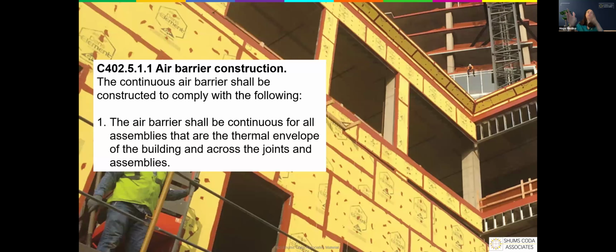All right, so air barriers. So now we're going to start hitting the sections that we're probably very familiar with. But I think after seeing what we just talked about, now these sections probably are a little bit more weighted in making sure that we get what we really need. Because remember, we do need that continuous air barrier. It needs to be continuous all the way around. A lot of times there's attention that's paid to it when we start thinking about the walls, right? But guess what? Those roof and below grade walls potentially could need to have that air barrier component also. So just remember, it goes beyond just those exterior walls.